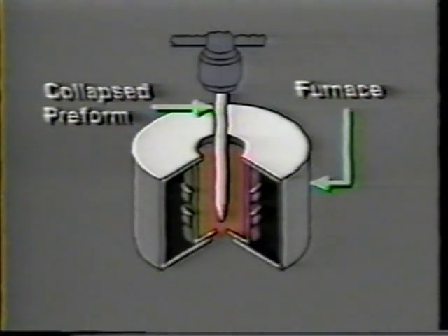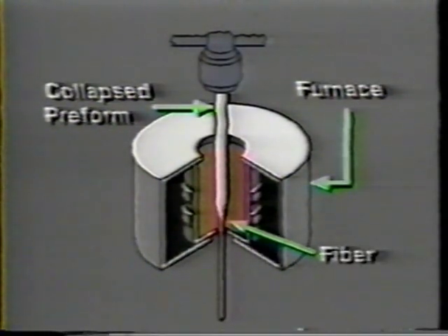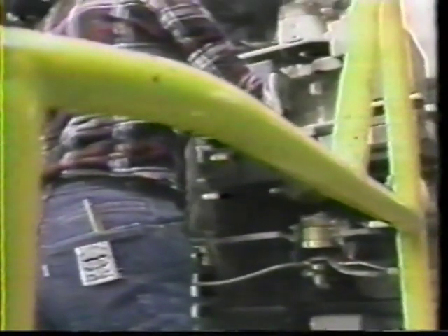In a few minutes, when the preform's tip is heated above its softening temperature, a technician can begin to pull fiber from below the furnace. Its diameter is being constantly monitored with a laser micrometer. The computer compares this information with a desired diameter and automatically adjusts the drawing pull rate once the fiber has been properly routed to a take-up spool.